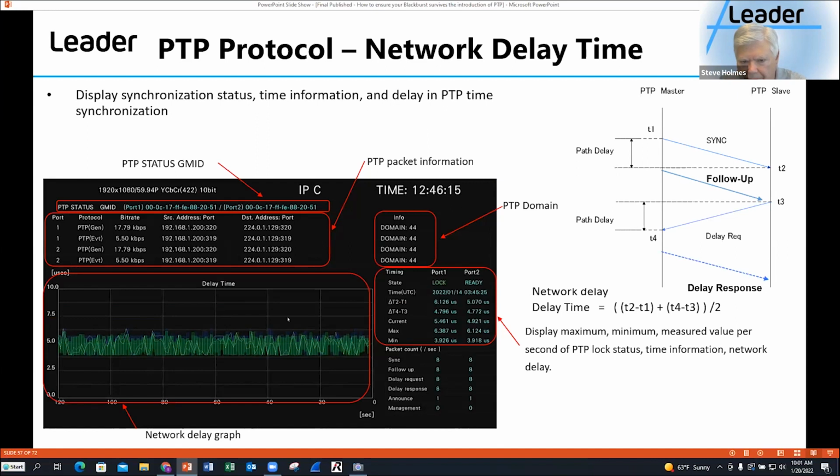The messages from the PTP generator to the follower are going with all the traffic. So this suggests to me that the switch architecture that I am currently going through, if this stays like this and gets bigger and bigger, that network is starting to get congested. And you need to start looking at, maybe I need more bandwidth in my network, that it's starting to slow down my PTP messages.